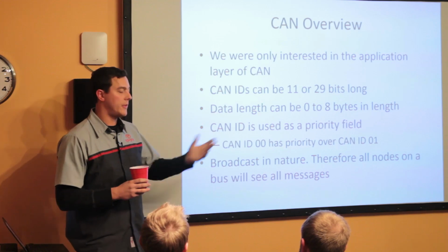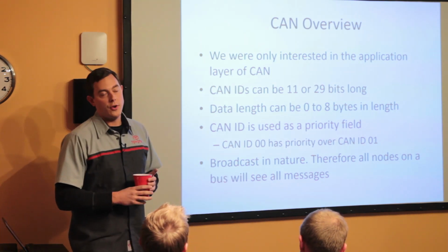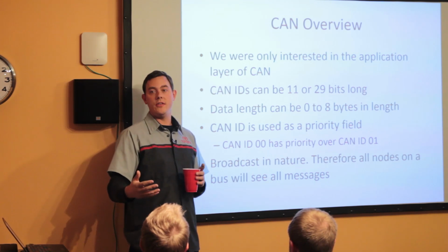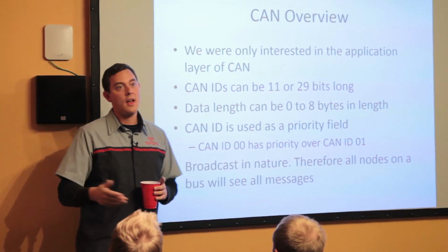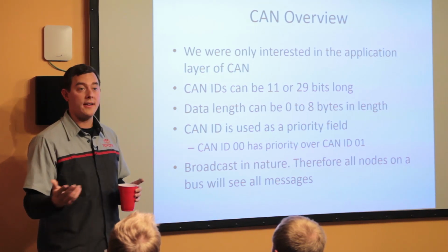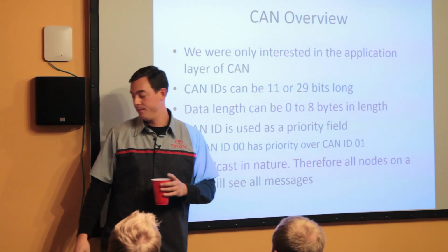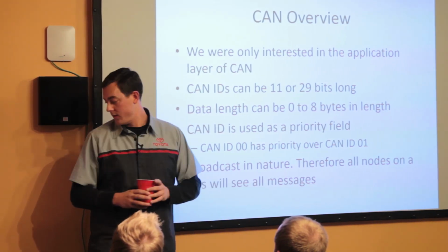As I said before, they're broadcast in nature. That means it just spits it out into the network, and whatever's there hears it. So you don't have to be, say, the steering ECU to send steering packets. You just have to be on the CAN bus. As long as you understand the format, which is usually proprietary, and the ID for steering, you can say, hey, turn the wheel at this angle, right? And again, that comes down to something that was just designed a long time ago.